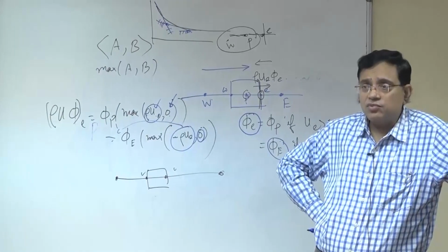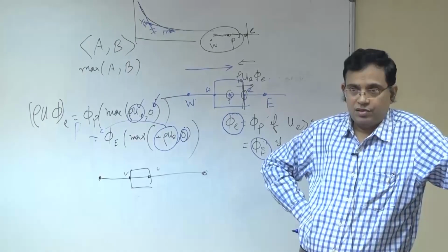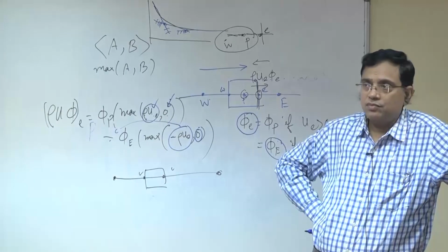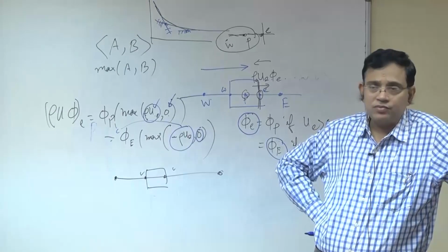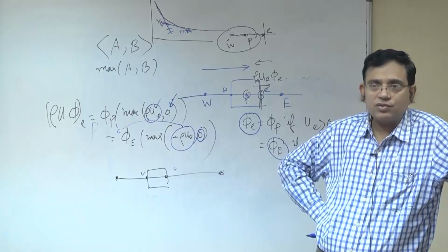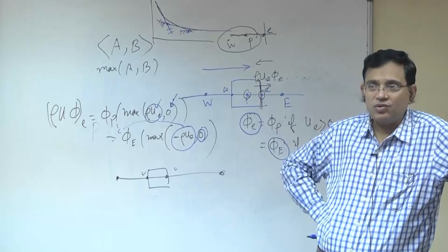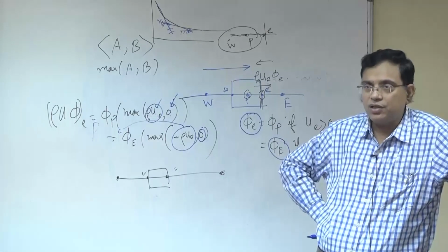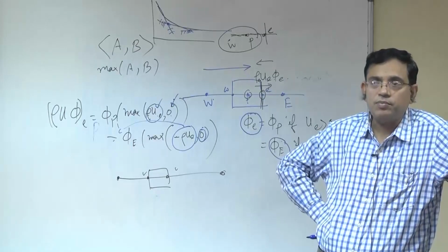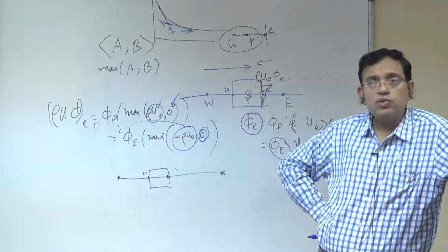But sometimes the exponential can also be represented approximately, not by an e-to-the-power form, but by a function with a certain power. That may give an approximation, and Professor Patankar found that with some value of that power, it closely reproduces this one, and that scheme he gave the name power law model. So, all these are motivated by the same fact.